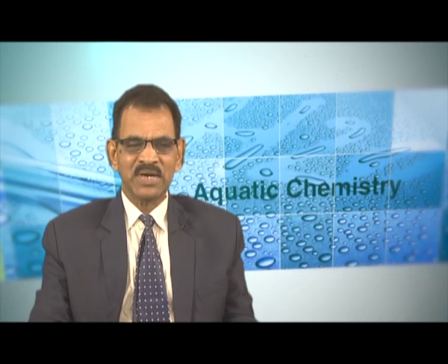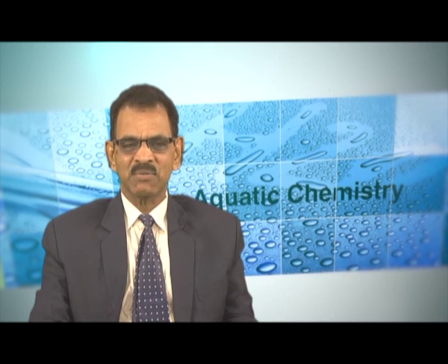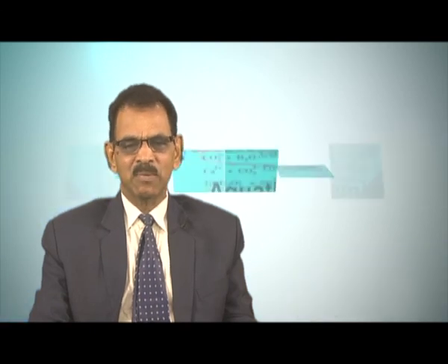And finally, ion exchange reactions are also possible in determining the mobility. Some toxic metals released into the water system may interact with the bottom sediments, which have considerable cation exchange capacity. In place of the adsorbed metal ion, H plus ions may be released into the aquatic system, which takes care of the buffering capacity and helps in the mobility as well as maintaining the pH value of the system.